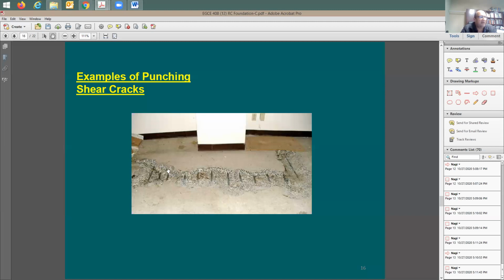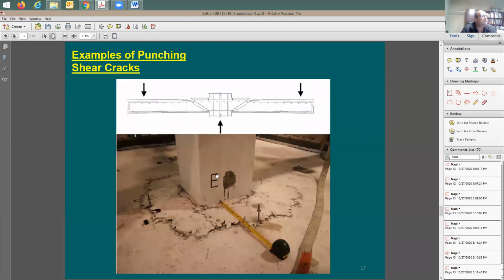And look here. After we have taken the carpet off, we start to clean all of this, right? At the beginning, of course, that was just cracks, but you need to chip it out, right? Chip all of this loose concrete, clean it. Now it is ready to be maintained and repaired. So this is the expected type of cracks. If the crack is only in one direction, this is not punching shear. This could be a shear crack or maybe a flexure crack. But if you see it around the column in certain ways, then you know that this is punching shear. It needs to be fixed in a certain way.